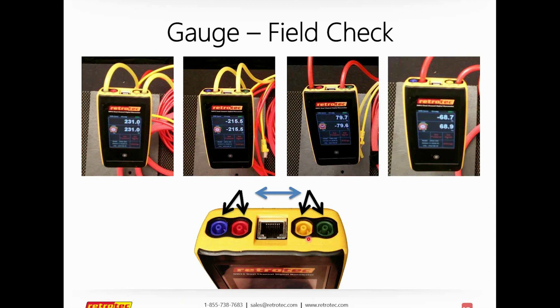So what you're seeing in this image is me taking one of my tubes and plugging it into one channel and into the other channel. You'll see I've got both channels set for pressure, and I'm getting the exact same number. When I push this tube onto the tap, it pushes pressure into the tube, and that pressure should be shared, so I should get the same reading from both sides. Then I've moved that tube to this tap, and the other end of this tube, and repeated this test over and over with all my different tubes. It's as simple as that.